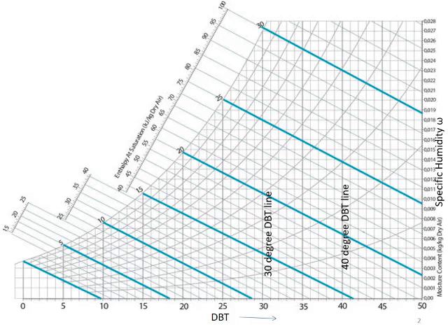So it is kg per kg of dry air. Through all these points, horizontal lines are drawn, equally spaced, from right to left. These lines are nothing but constant specific humidity lines. Specific humidity remains constant throughout that line.